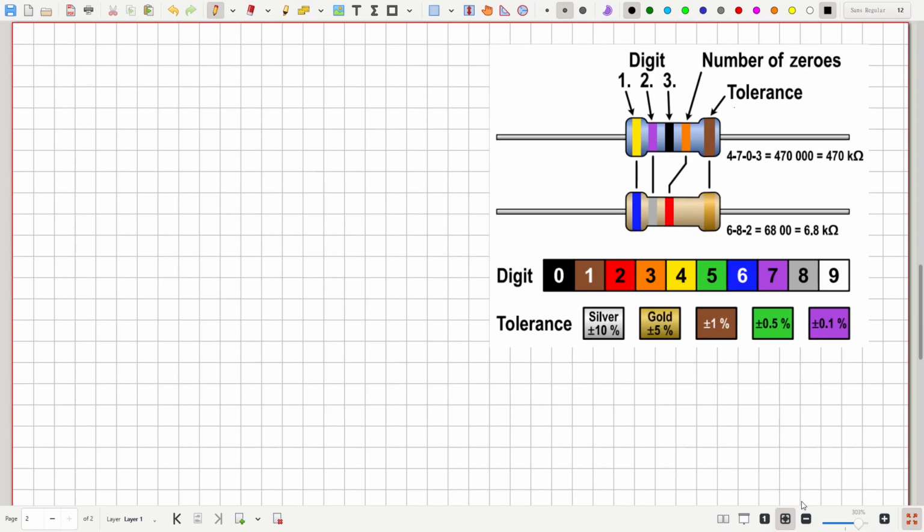Resistors are generally too small for us to be able to write or print legible numerical values on them. Therefore, we use the so-called resistor color code to indicate their value, their resistance. And here's an illustration of that. This is from the Wikipedia page on resistor values. And there are two common types based on different tolerances, so that we can only build a resistor to within some finite uncertainty, and it usually costs more money to make a more precise resistor.